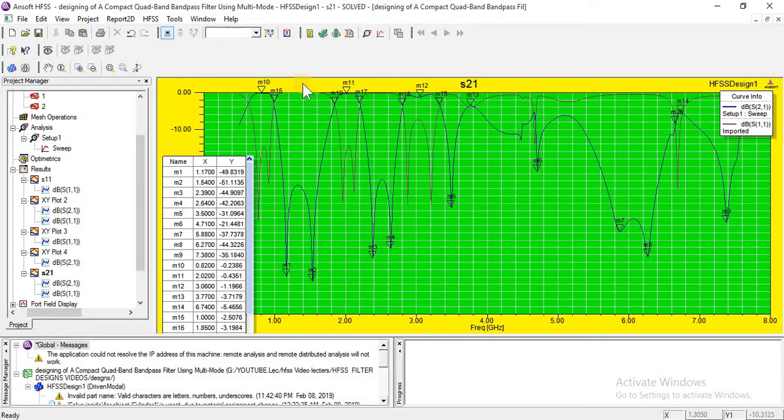Here you can see that for fractional bandwidth we always mark -3 dB, because the S11 and S21 graph always touches at -3 dB. We are discussing a practical bandpass filter, and in a practical bandpass filter it is not possible to create a passband or stop band at an exact and ideal position. Because of reality, we always take -3 dB. Here I have marked for first passband.